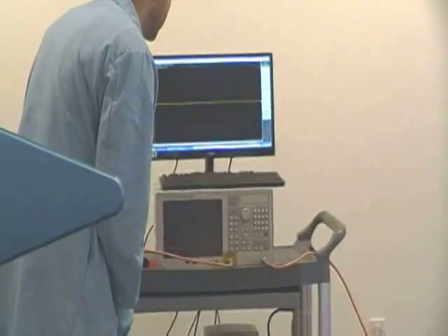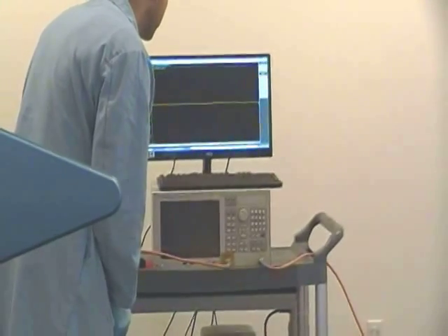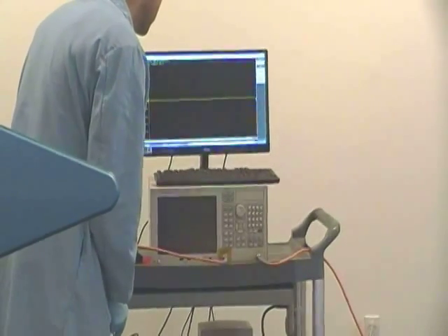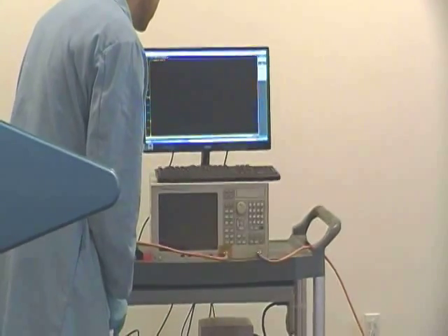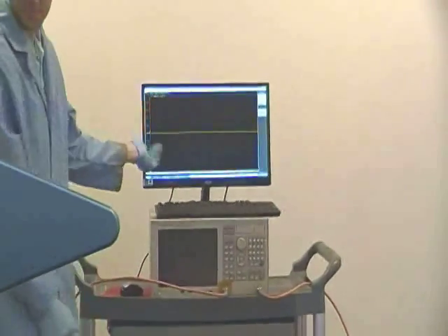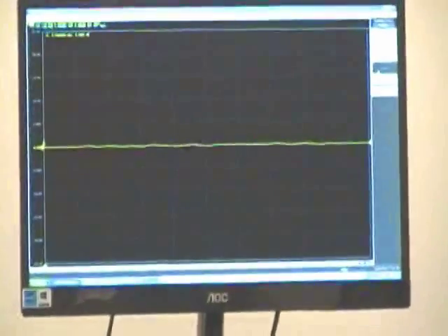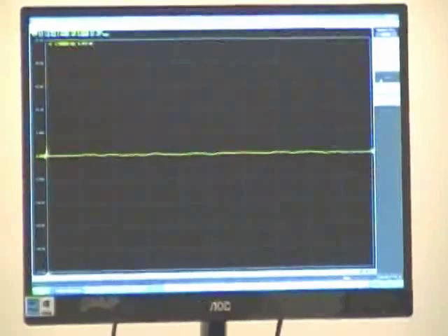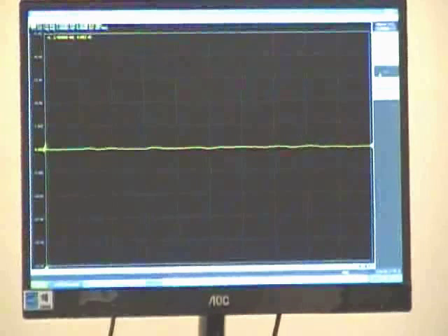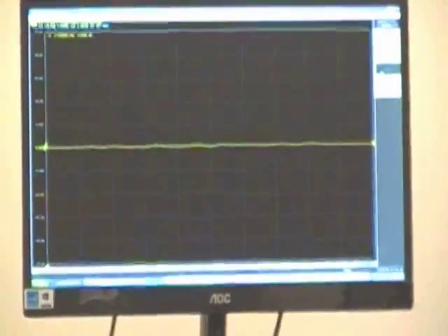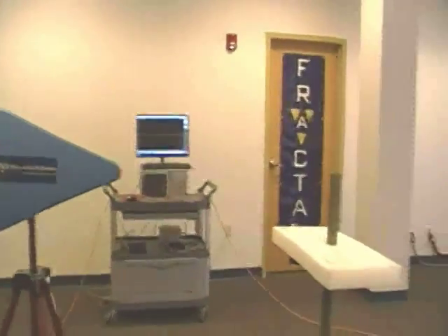And now he's going to do the calibration by normalizing the intensity between the two antennas with no obstruction. Steps are 5 dB, and this now constitutes the direct path. Any obstructions will cause the measurements to go down in intensity relative to this 0 dB line. Here's a zoom of that normalized direct path trace. By the way, we're going to save all traces at the end to show you the three cases all at the same time.